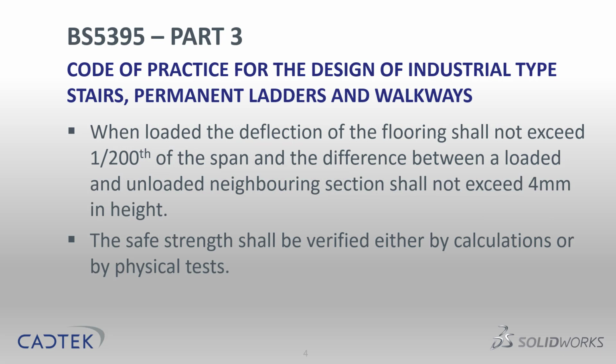Apart from the obvious mechanical failure, we also need to make sure that the floor does not deflect more than 200th of the span, and also that any loaded and unloaded neighbouring sections do not exceed 4 millimetres. More importantly, the standards dictate that we need to verify our designs either by calculations or physical tests. In other words, we can use SolidWorks Simulation to check our designs rather than having to build physical prototypes and test every time.